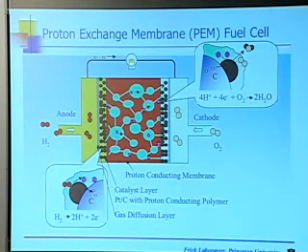Okay. And you're making water over here. And, of course, you don't want water just over here. You want it everywhere. And it turns out, in order to do that, you don't make enough water because you're not making it in the right place, really. And so you have to humidify your gases. In particular, you really have to humidify this hydrogen side, but typically you humidify both sides. Okay. But you don't over-humidify because then you'll get flooding. So this is a nice engineering trick.